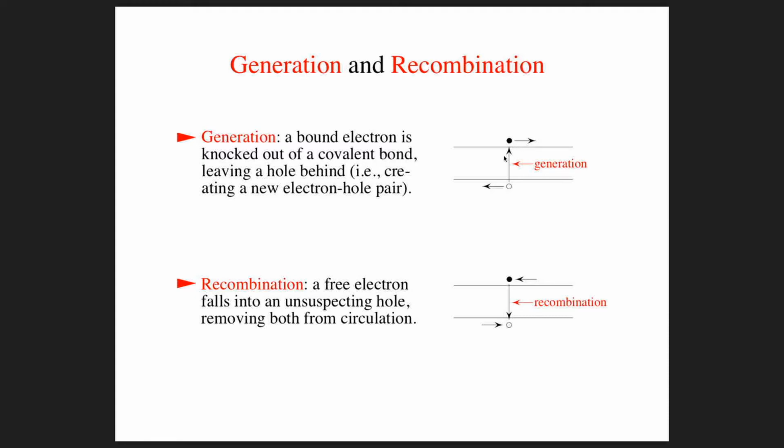through some means. And so this sort of generation event can happen thermally, that's called thermal generation, and it can also happen optically, that's called optical generation, and there are other possible ways that can happen. We're not going to be necessarily concerned with quantitative modeling of this type of phenomenon, but it and its complementary process here, if they are modeled quantitatively, typically follow first-order reaction kinetics like you would find in chemistry.